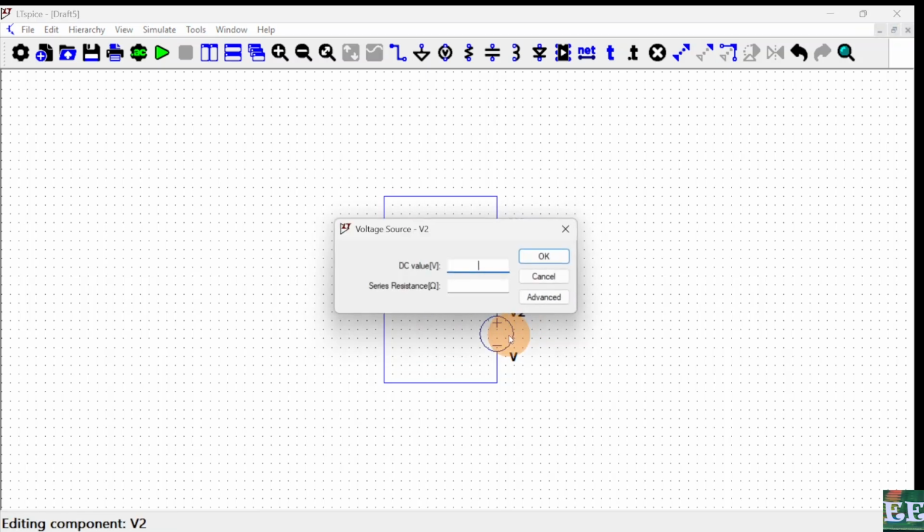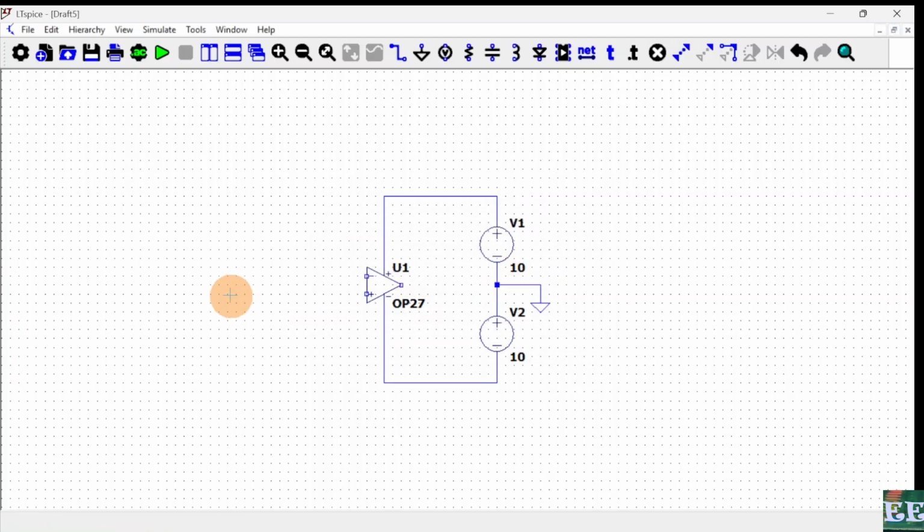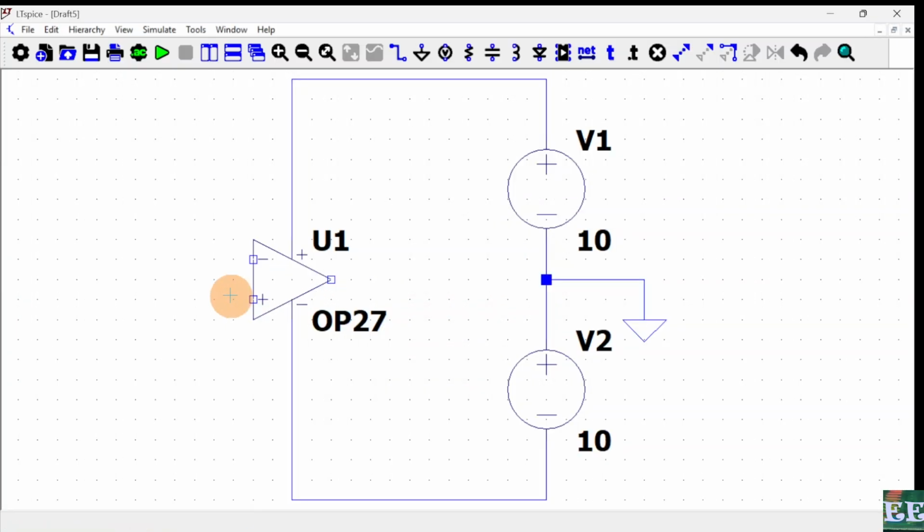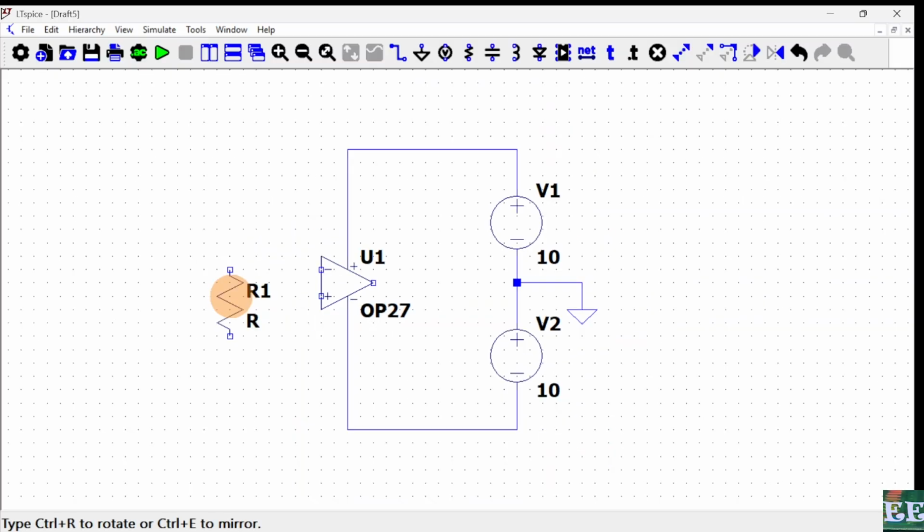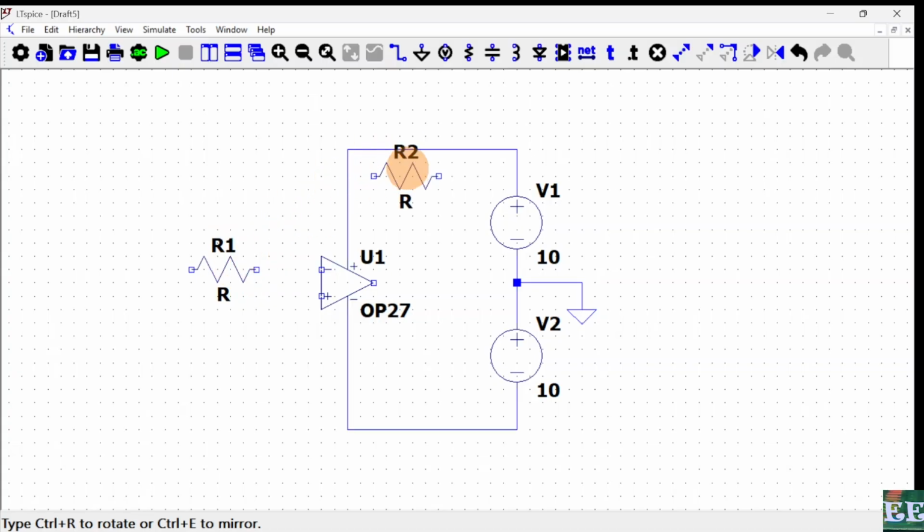With that complete, the signal portion of the circuit can be constructed. I'll start by placing 3 resistors. Pressing R allows me to place an input resistor. If it is necessary to rotate a part while in place part mode, Ctrl R will rotate the part. Left-clicking places the resistor.